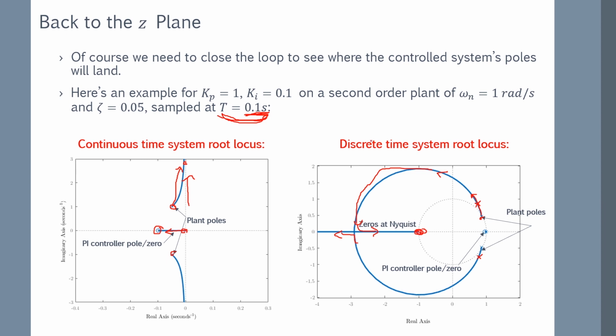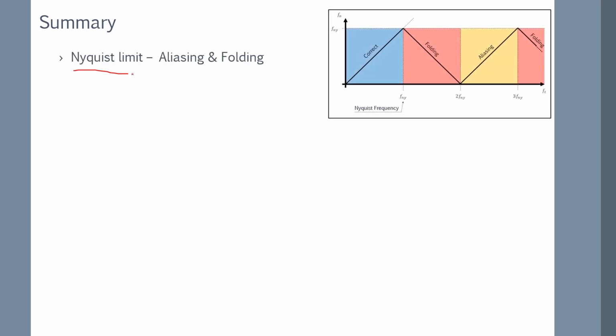Okay, so I think this is enough. This is long enough, definitely. And I'm just going to finish this by summarizing what we looked at. So we went through the Nyquist limit, the folding and aliasing effect, and we looked at the folding diagram. I think this is a rather important diagram to have in your mind when you're designing control systems, and especially when you're filtering your signal to make sure you get rid of all of this crap, because this hurts your controller's performance. If you think about it, if you're trying to make a controller and your frequency is here and it appears here for your controller, it's trying to control something that is not really controllable for the controller, which means that it's going to fail and maybe even make the system unstable.